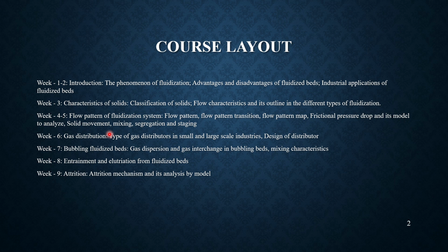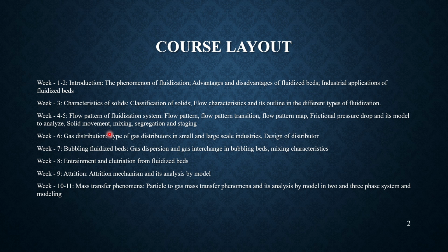And week 9 it was about attrition mechanism, because since we are dealing with solids and they are moving similar to a fluid, it is very much essential to understand how solids are getting corroded or eroded. Therefore attrition mechanism is very much essential, because the solid can be fragmented or broken into smaller fines, and there are so many phenomena happening behind the name of attrition of the solids. When we are dealing with valuable materials, it is very much essential to understand what is happening a priori, so it would be beneficial during the process, so that we can avoid the loss of the material and so on. And week 10 to 11 it was about mass transfer phenomena happening inside the bed, because we have almost two phases in general. If we are analyzing the fluidized bed using a model, we have a bubble phase and the emulsion phase.